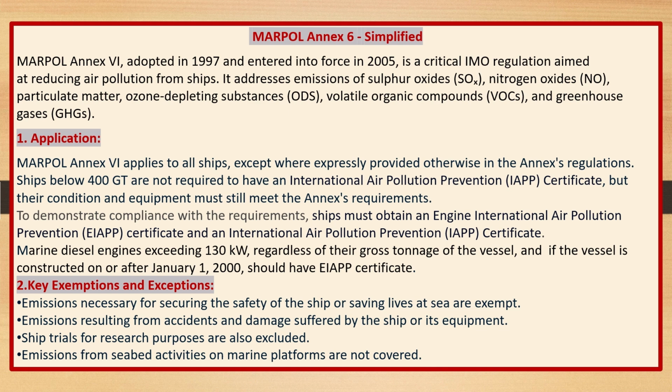1. Application. MARPOL Annex VI applies to all ships, except where expressly provided otherwise in the Annex's regulations. Ships below 400 GT are not required to have an International Air Pollution Prevention (IAPP) certificate, but their condition and equipment must still meet the Annex's requirements. To demonstrate compliance, ships must obtain an Engine International Air Pollution Prevention (EIAPP) certificate and an International Air Pollution Prevention (IAPP) certificate.